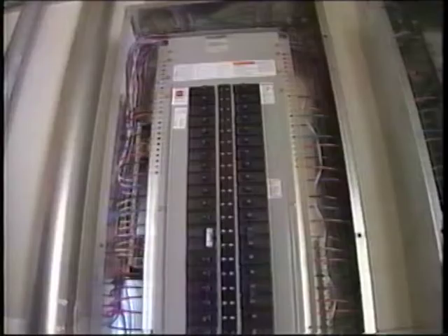To avoid accidents, your first protection is to make sure your electricity is properly grounded. This means creating a safe path for it, away from your body, and containing it within the equipment or tool you're using. Fuses and circuit breakers help protect cords and equipment, while ground fault circuit interrupters, or GFCIs, protect people. GFCIs are required on all temporary power at construction job sites.